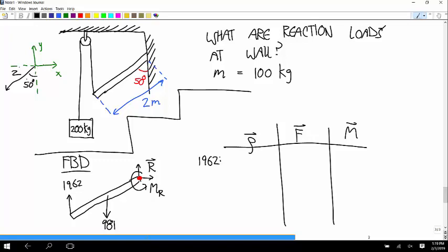So that's going to be 2 times cosine and sine of 220 degrees, which is negative 0.766, negative 0.643, times 2. 2 times negative 0.766 is 1.532.